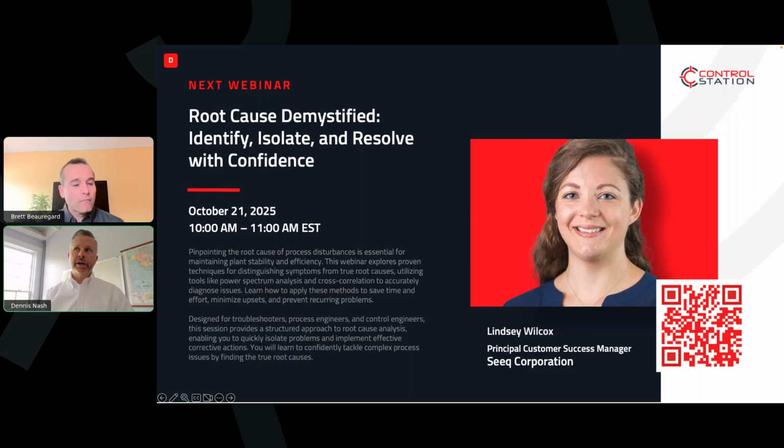As the non-engineer here, I'll chime in that I too conceptually like the doublet, the idea of moving up but then also moving below set point, revealing the potential differences in behavior. If you think temperature loop, heating is different than cooling. And so through that doublet, you may explore different and even competing dynamic behavior and establish tuning parameters that accommodate both aspects of a process's dynamics.